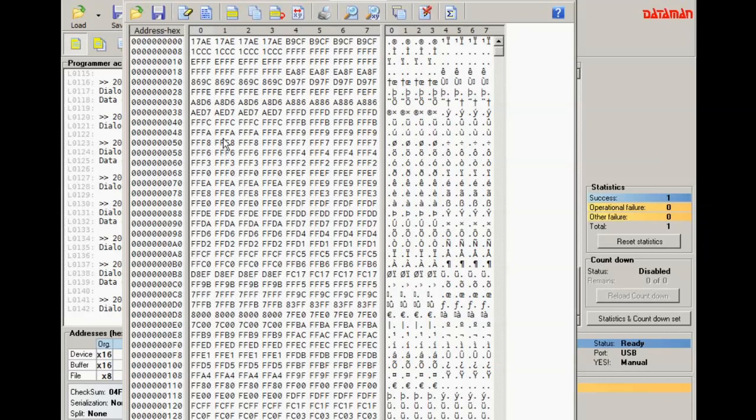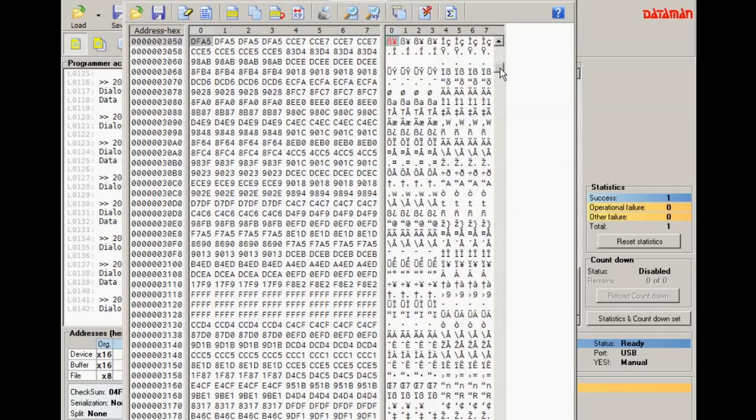But just as a kind of sanity check, I just want to check a few key addresses. The first one is the first address, of course, but bear in mind that we have 4 readings in this buffer per address, so we need to multiply the addresses we're looking at by 4. Now the next key address was 815 hex, so if we multiply that by 4, we need to look at 254 hex.